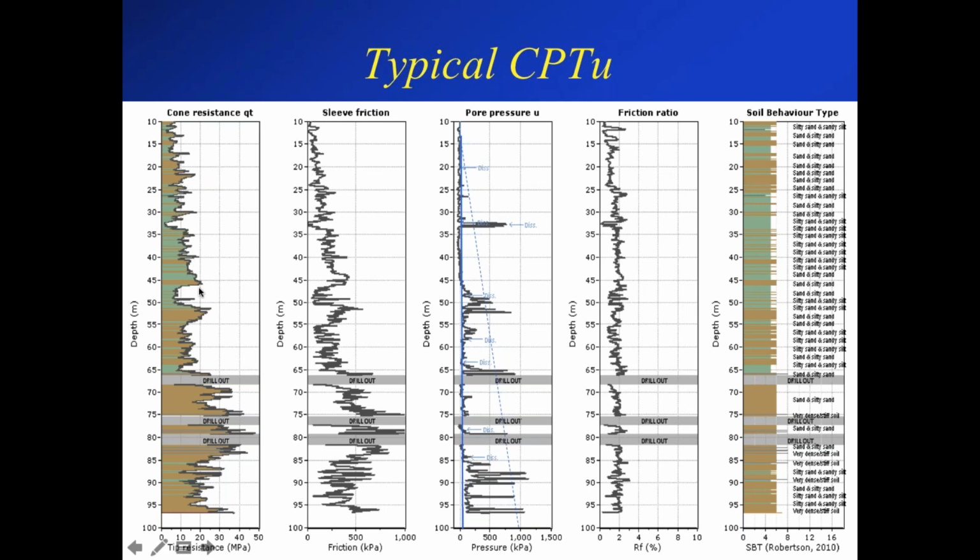Here from about 34 down to 46 meters is probably one of the lifts, and then a slight drop. And you also tend to see that where that drop occurs at the boundary between different lifts, you tend to see a little spike in the measured pore pressure during cone penetration. And so that may be where some fines accumulate at the end of the lift due to maybe some trafficking of material as well as erosion, etc., that creates a fine covering on top of the lift, and then of course that's reflected in a slight buildup of pore pressure when the cone pushes through.